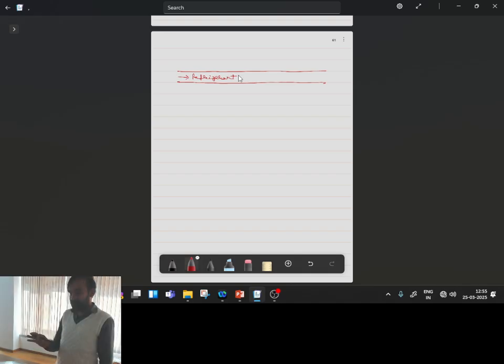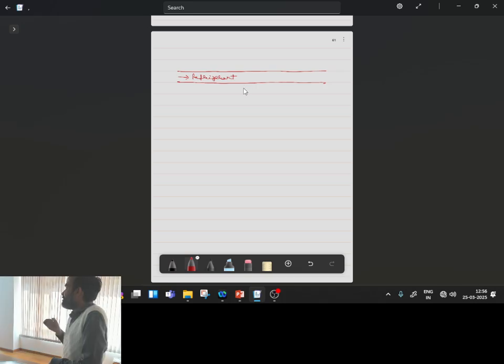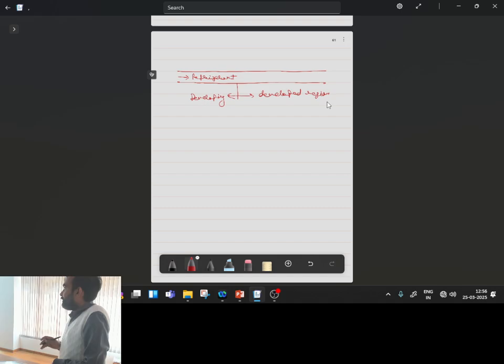So the first point is, my experimental facility should involve a straight tube, and the other point is, the length of this straight tube should be such that for the measurement the flow is developed. Say if at this point flow is entering, then I will have some developing region, and then I will have some developed region. Okay, is this one clear?